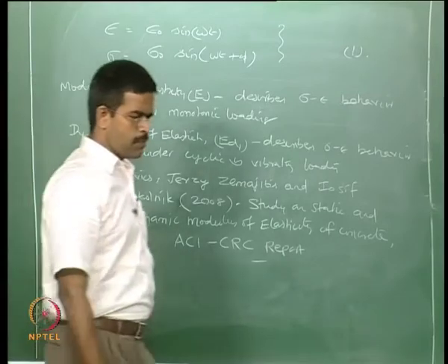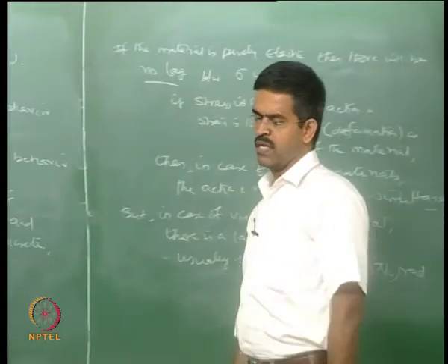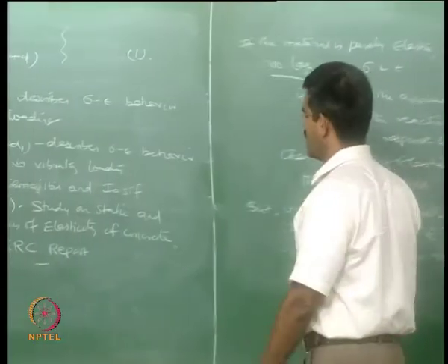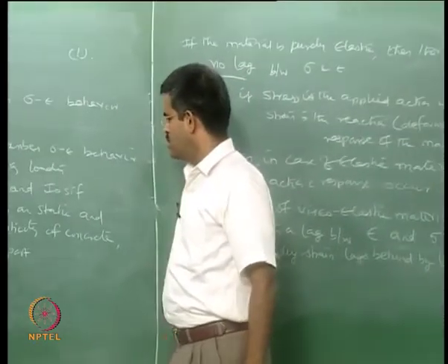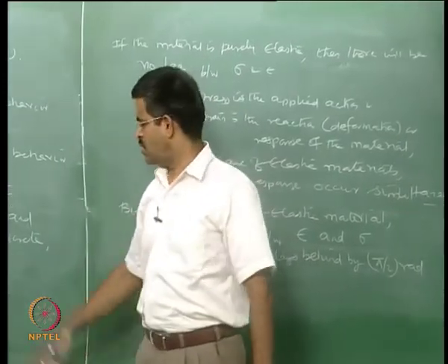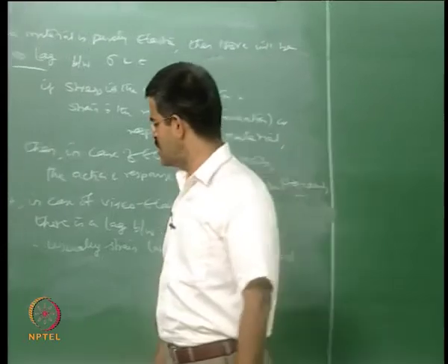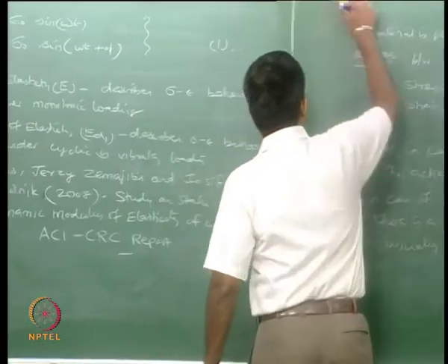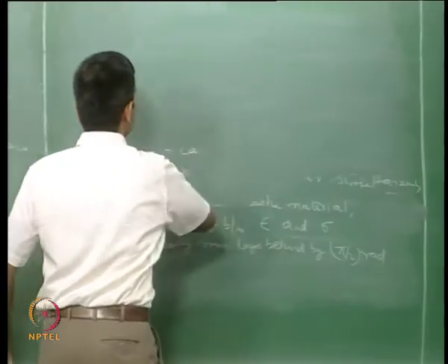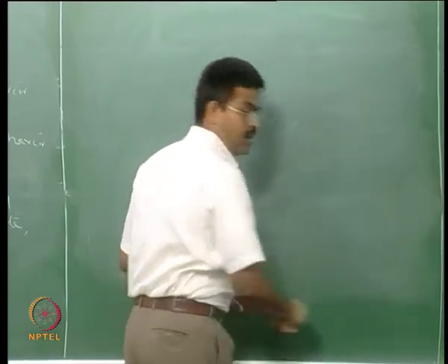There is a very interesting report given by Popovics et al. in 2008, explaining the difference between the characteristics of modulus of elasticity and dynamic modulus of elasticity on a specific material, concrete. He has listed various factors which influence dynamic modulus of elasticity of concrete as a material, or for any material in general, are the following.